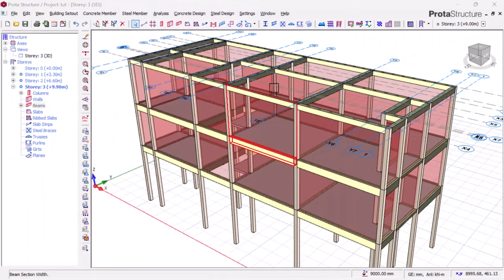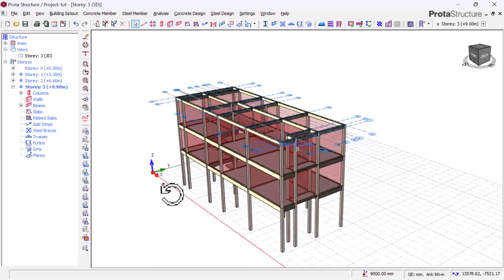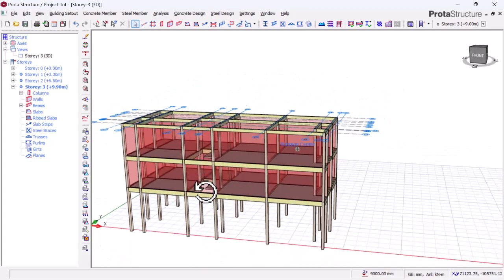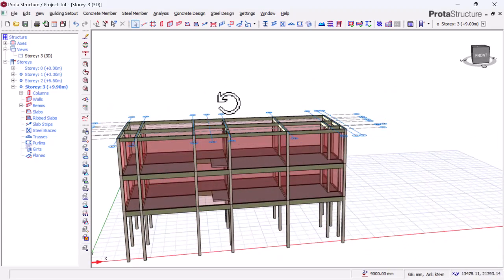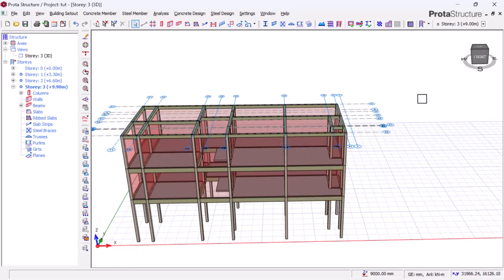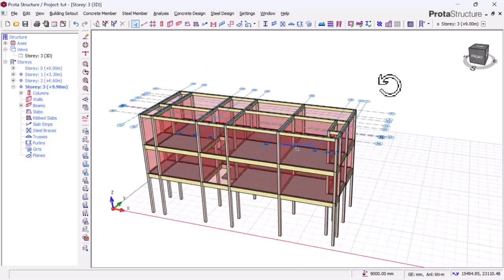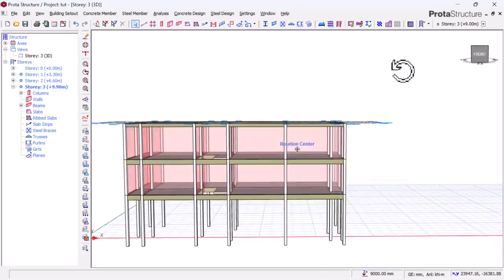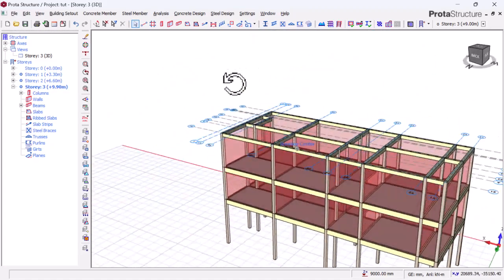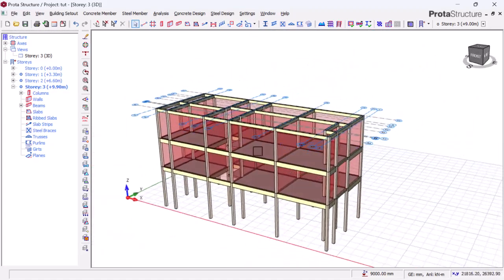So when you have a longer span at your roof level, it is advised that you take note of the span and look for a satisfying depth to befit the span for the roof. It mustn't reduce to this level. Everything you're going to do has to depend on the kind of structure you are doing, so you must consider that depending on the type of structure. But since we are looking at this simple structure, we just have to stick to this dimension.